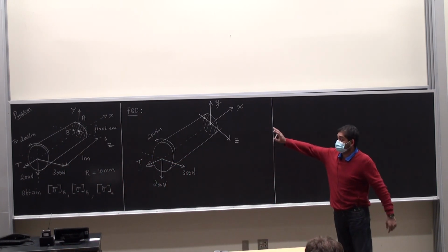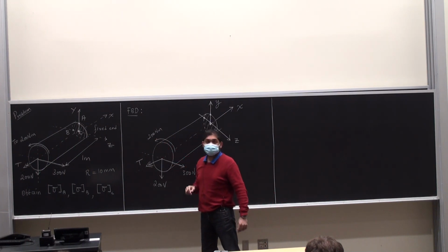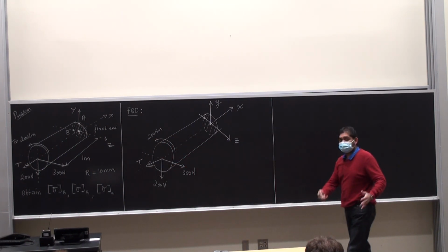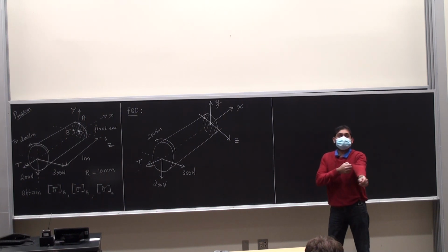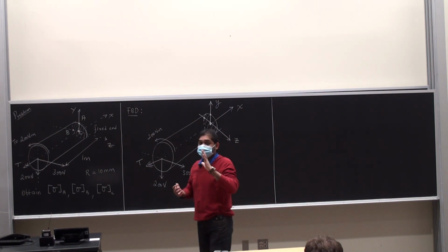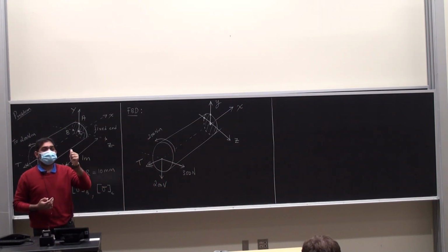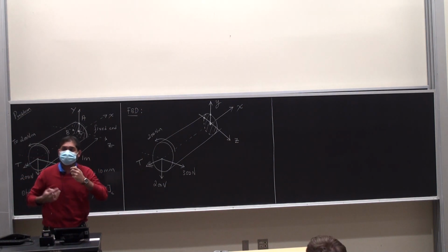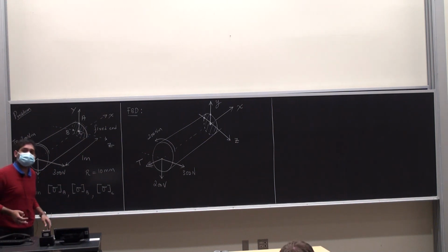But that coordinate system was not given to me to begin with, you see. So they make me think, okay, what's the best coordinate system for it? Anything that you're convenient with. And then I start marking all the reaction forces and reaction moments at the fixed end. Because it's a fixed end, how many reaction forces are going to be there? 3. One along each axis. How do you draw the positive reaction forces? You just point them along the positive axis directions, that's all.